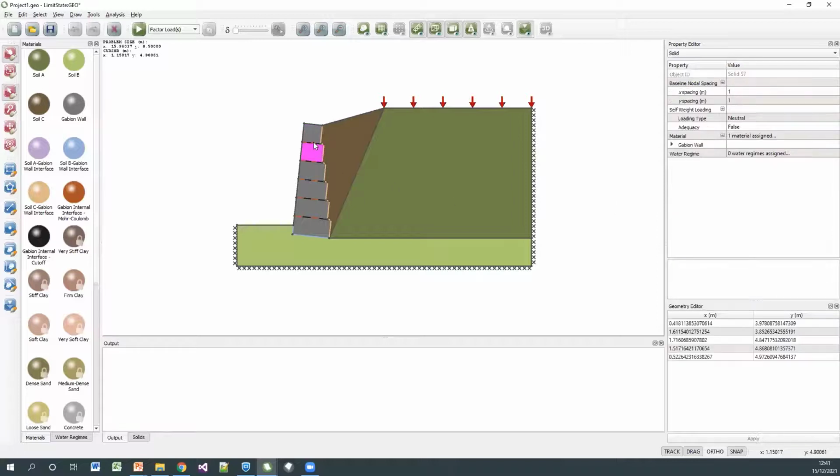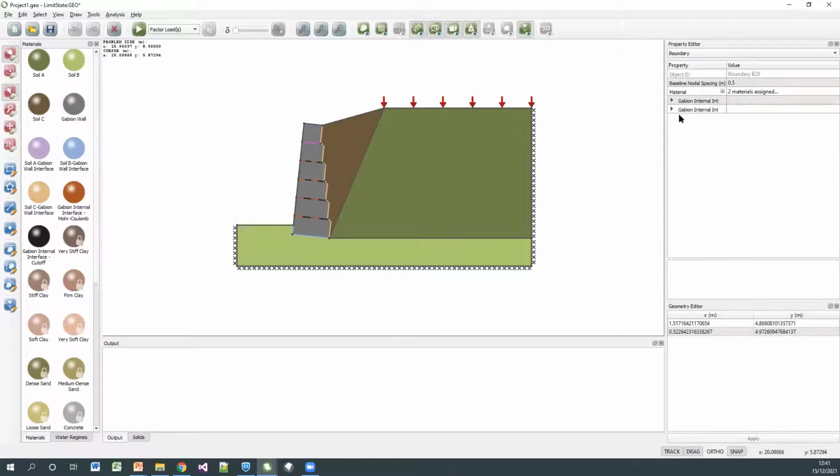Critically, on the interface between two gabions, we have two materials modeled, one called a Mohr-Coulomb material, one called a cutoff material. We'll come back to those later on, but they essentially allow the gabions to slide or rotate or crush at the corners.